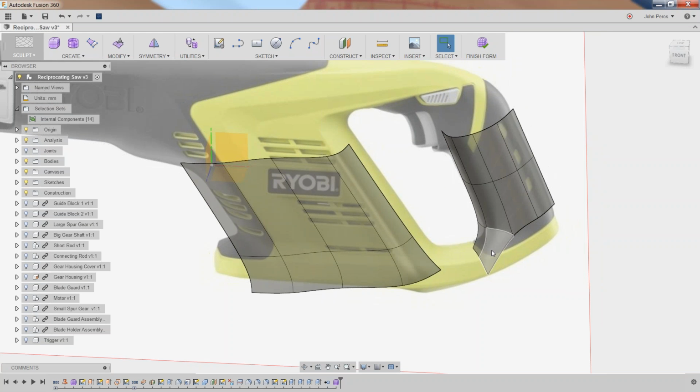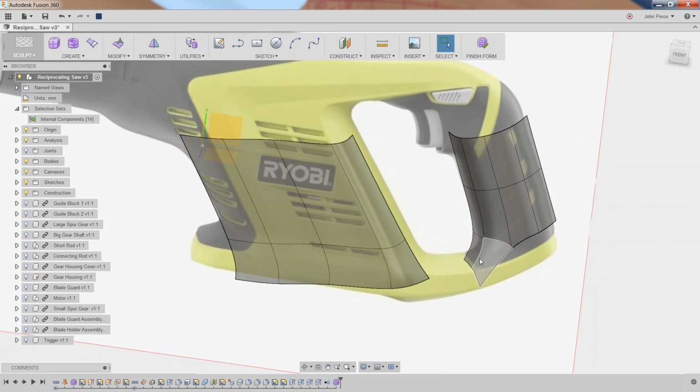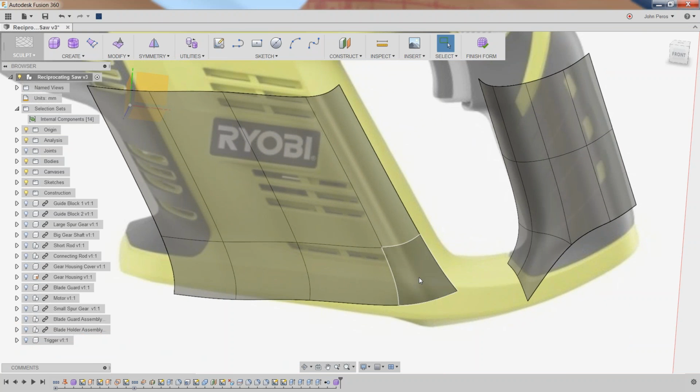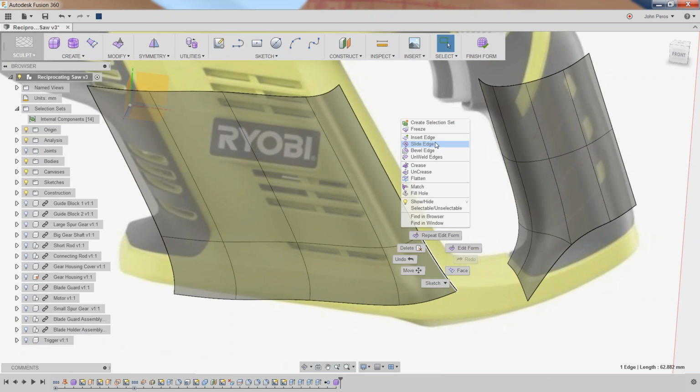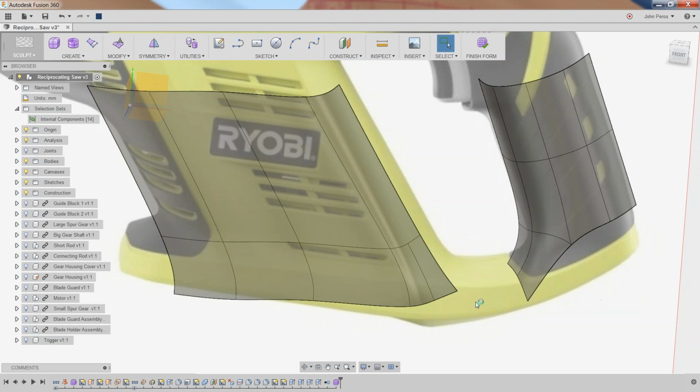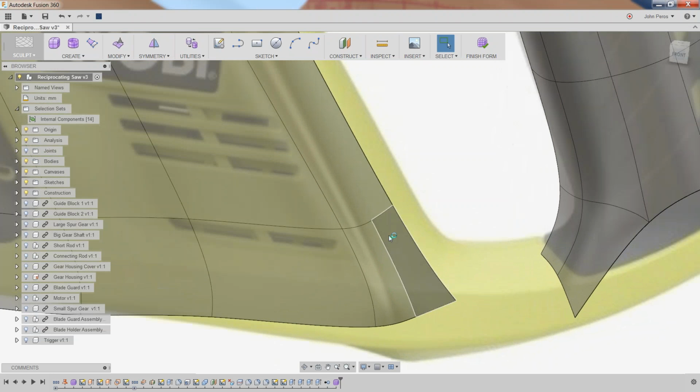And you can probably see what I'm starting to do here is I'm going to build a connection between these two bodies. But one of the things with subdivisional modeling is you want to match faces. So I've got two faces over here and only one face here. We utilize a special mathematics inside of Fusion called T-splines, which will allow me to insert finite detail in specific regions of the model, creating essentially a T-junction. That's what this point is right here.